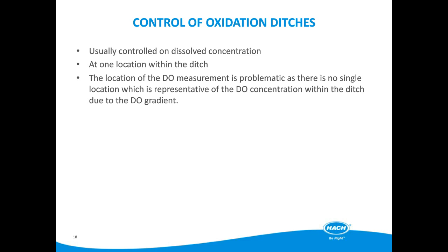The amount of air being introduced into each section or zone of the lane is controlled by a number of diffusers in the zone, with the highest density being at the start, and also controlled by limiting the volume of air being supplied to the diffuser grid. This is not the case in an oxidation ditch, where the contents again are fully mixed, and as the mixed liquor is transported through an aerated zone, the DO increases. After exiting that aerated zone, the DO is depleted as the biomass consumes oxygen. A diagrammatic interpretation of this is shown in the following slide.